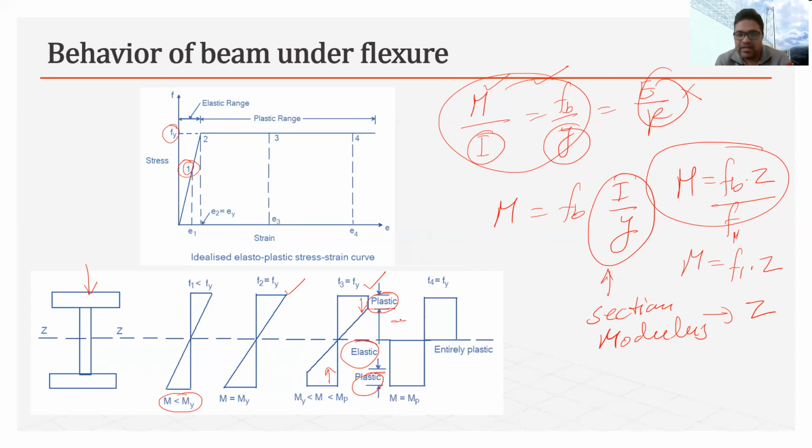So you can see the next diagram. In this we can say that the whole material of the beam is yielded. Similarly here also the whole material of the beam is yielded, and at this stage the moment of resistance, or the strength of the beam, if such a condition occurs in the I section, will be equivalent to the MP value. Now MP is the plastic moment, and at this stage the hinge in the I section will develop. That I will show you using the diagram.